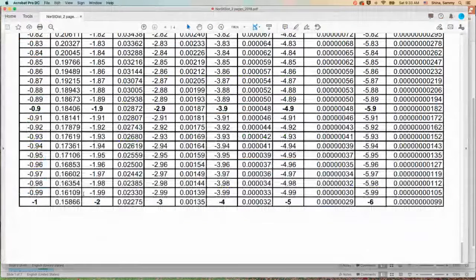So if you look at the Z chart and you look at 3, right? 3 is the 3 sigma point, and if you have a point outside of the 3 sigma point, its probability is 0.0135, or 0.135%. If you do it on both sides, then it is 0.27%. That translates to 2,700 parts per million.